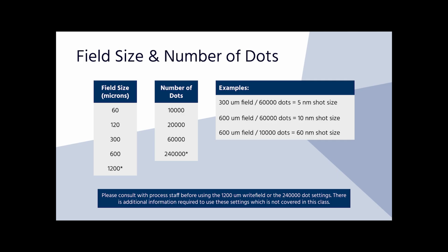Please consult with process staff before using either the 1200 micron write field or the 240,000 dot option, as there is additional information needed to properly use these settings that I am not covering in this video.